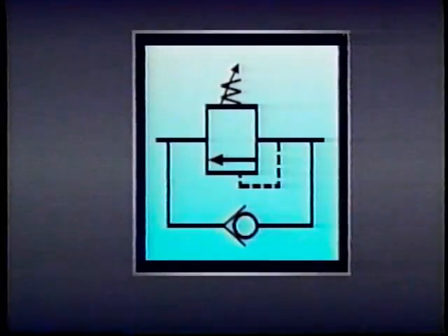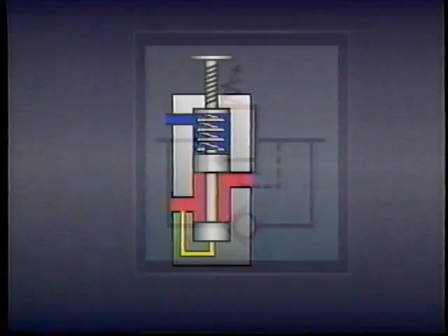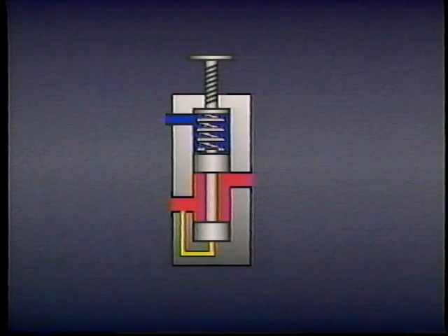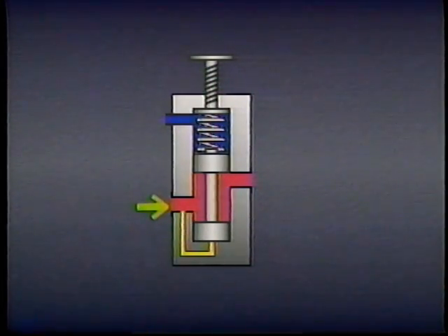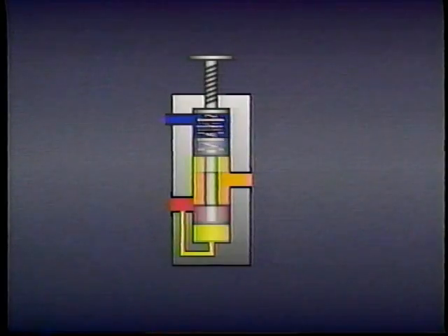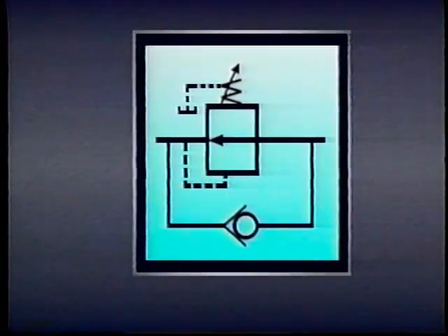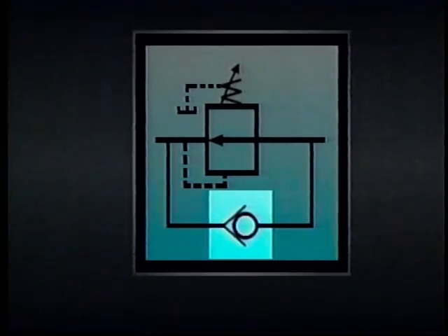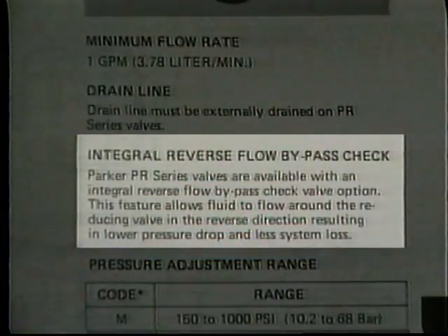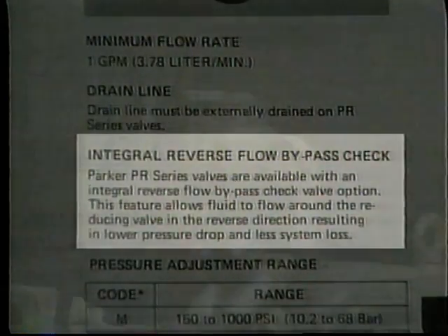The same technique is necessary for normally passing valves like pressure-reducing valves. Even though they sense pressure at their secondary port and might continue to pass fluid under reverse flow, any rise in pressure could close the valve. Therefore, check valves are used with normally passing valves as well. Very often, these check valves are included in the same housing as the pressure control valve.